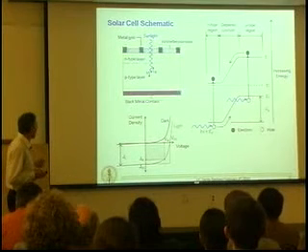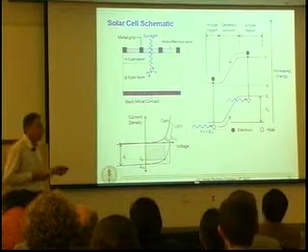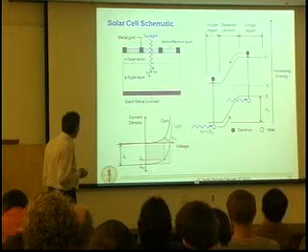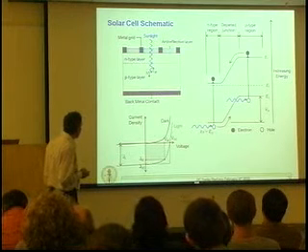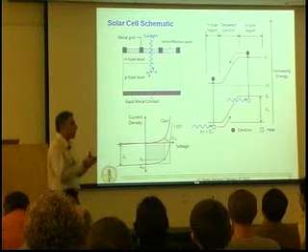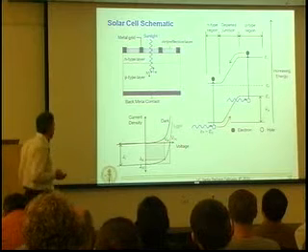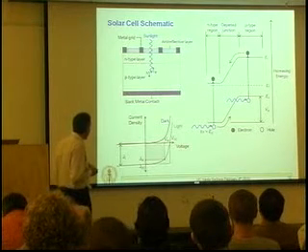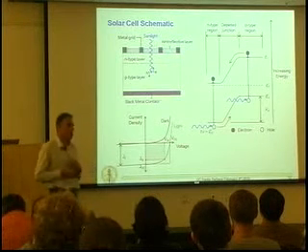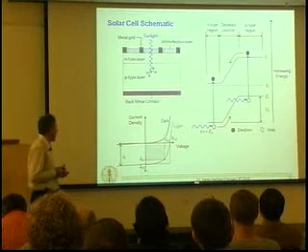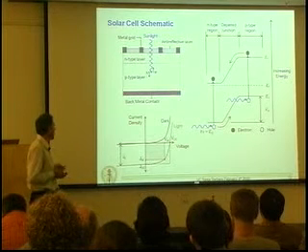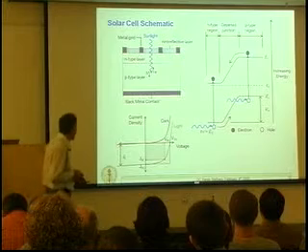And so there's some internal source of a dipole field. There are various ways to make this dipole field that produces the charge separation. So we have to have a cell whose physical thickness is thick enough to absorb the light, and thin enough that the photoexcited charge carriers make it to the external circuit, or to the charge separating junction. So that's basically what we need. And in fact, almost all of the cost, technology development, and all of the paths that we've used for materials development are guided by these constraints in photovoltaics.